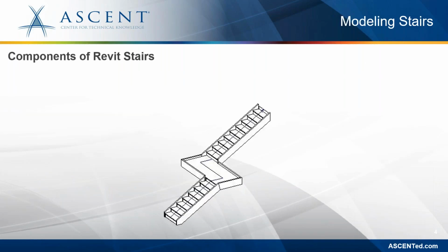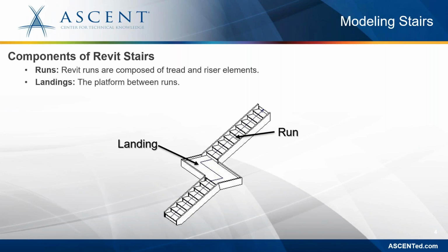All right, so as with other Revit elements, stairs are smart parametric elements. The stairs are a system family, but also contain component families, which can make the stairs tool feel more complex than other system families. Stairs can be created by assembling stair components or by sketching a custom layout. To break it down, the runs include the straight runs that can be combined for multiple landing stairs, spiral stairs, L-shape, U-shape, and winder. The landings are typically created automatically and then modified as needed, but they can also be created independently of the assembly.